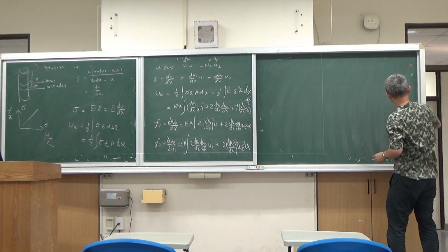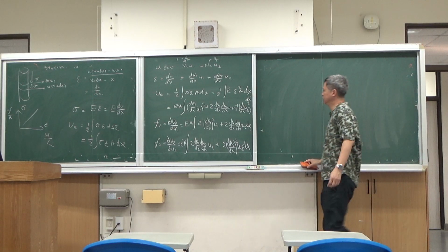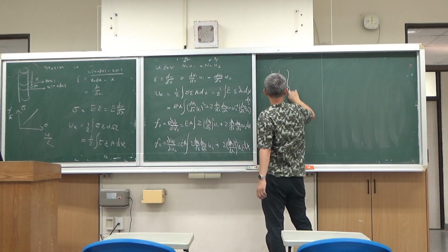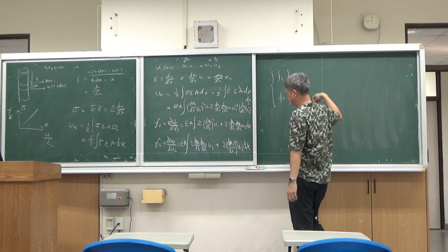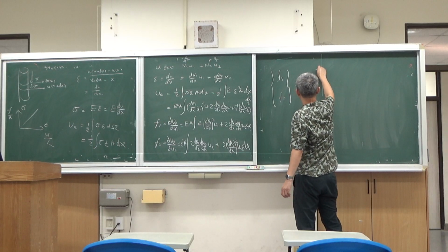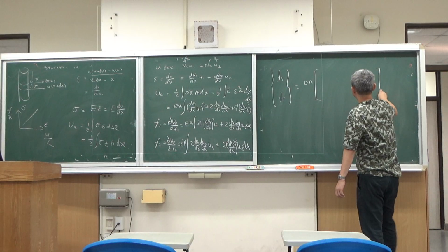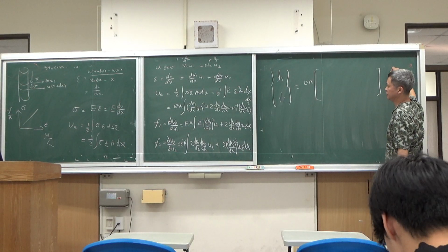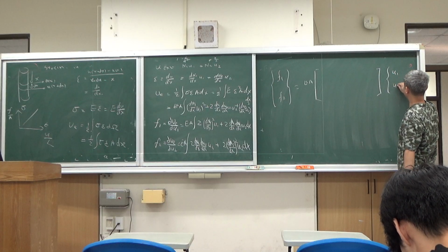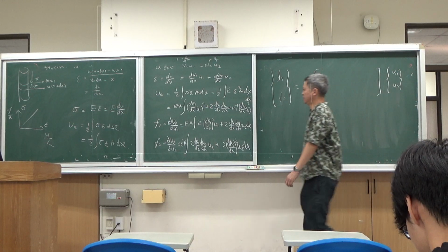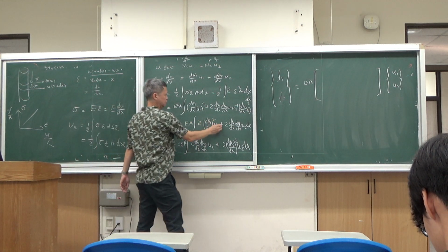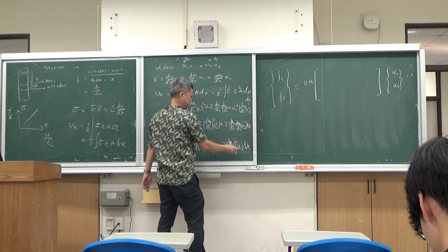Okay. So with this, now we can write the force into the matrix form. So you are writing force 1, force 2. And what is the second term? The second term is EA, a stiffness, times u1, u2. Let's identify the gradient and variable u1, u2.